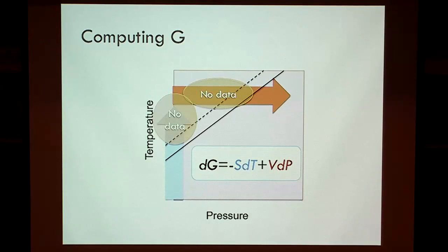What I've also done here is indicate schematically where the melting temperature might be along this black line here. And I've also indicated a dashed line where materials, eventually, most solids become actually elastically unstable. Nasty things happen, like the bulk modulus vanishing or the shear modulus vanishing. And so above that dashed line, the Gibbs free energy is actually undefined.